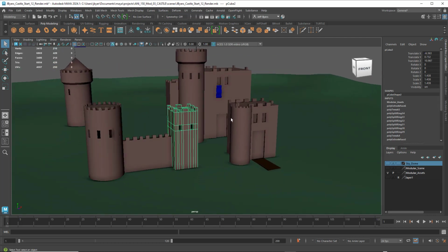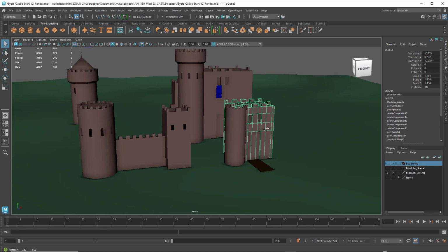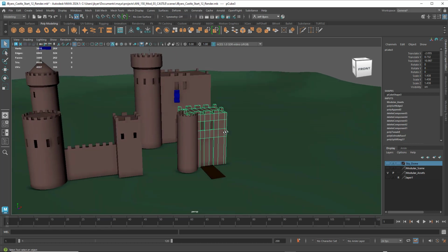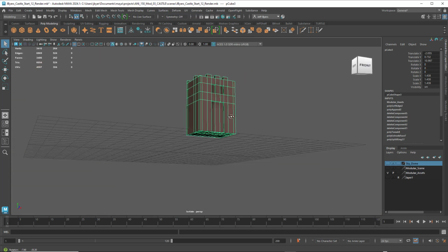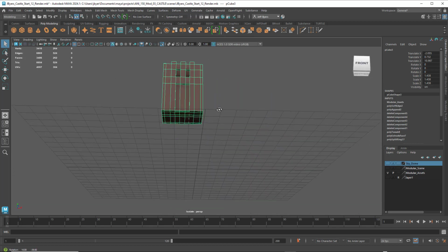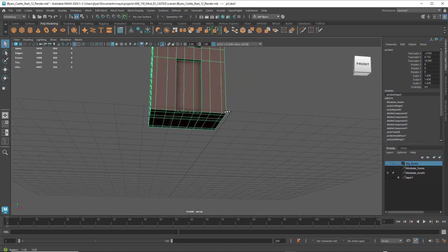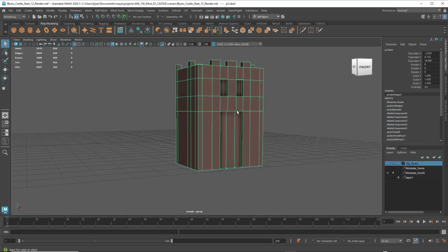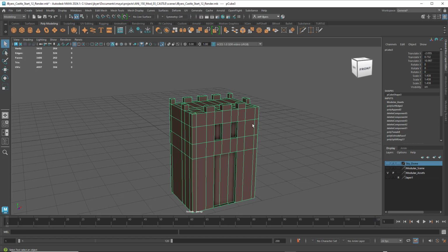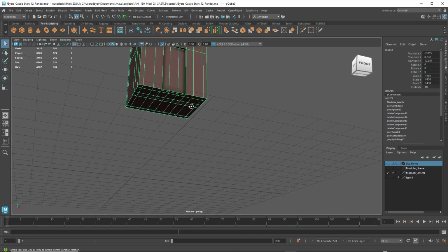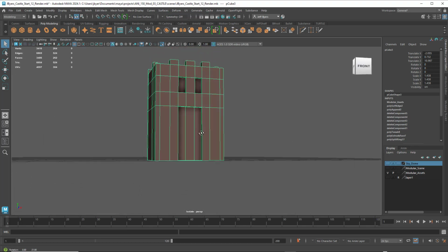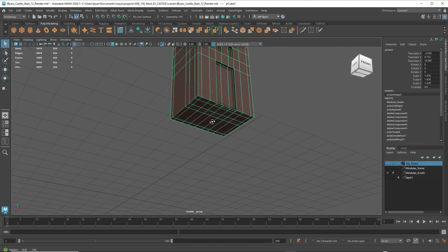I don't care where we start. I'm going to start over here and move our way over like this. Each one of these pieces will have its own UVs. So we're going to do a Control 1. Select this piece right here, and do Control 1 to isolate it so we can see all of the sides. Now normally I wouldn't even do the bottom of this object because you're never going to see it, and it's never going to be tipped over. So we could take all the faces off the bottom to save some face count.